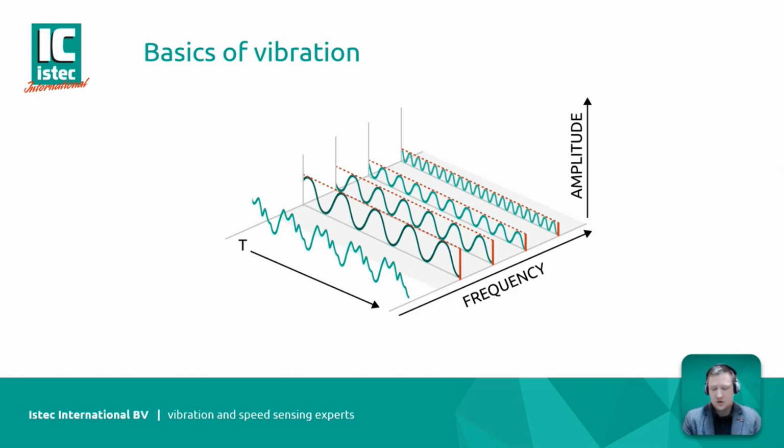That is a commonly used representation of a vibration signal during the processing and analysis of vibrations. But it's also important to keep in mind that there are limitations in using the fast Fourier transform. For many causes of vibrations, though, it's a very important tool because it gives insight into the different components of the signal very easily, and it's very easy to understand.